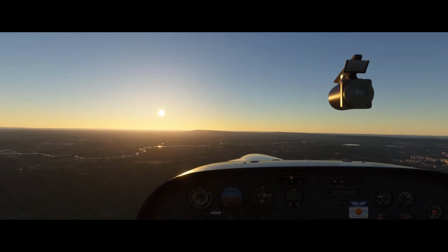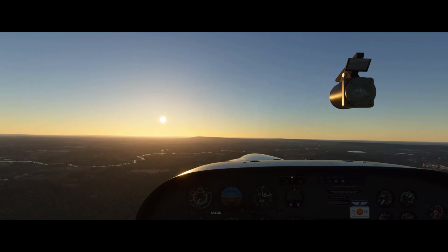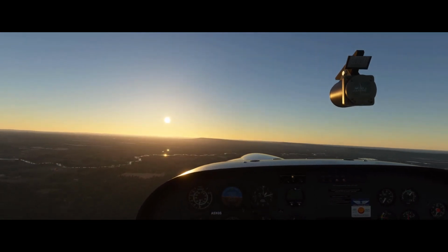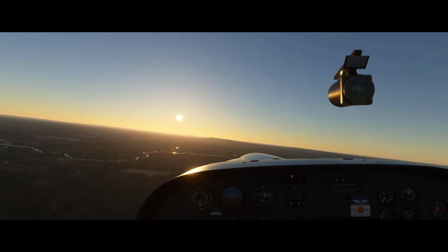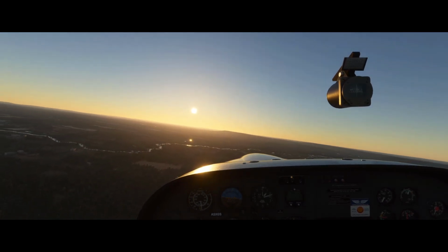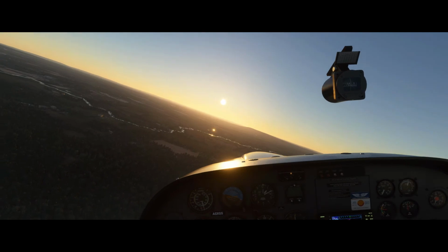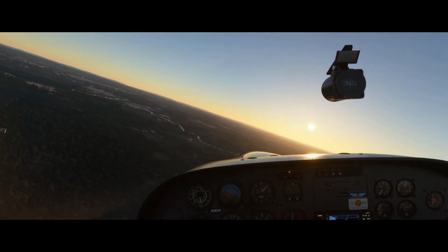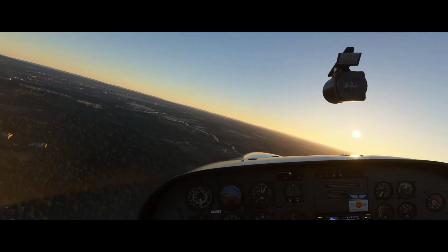So what we do here is we want to get into the white range for the flaps, which are on our airspeed. So I've pulled the power right back, maintaining altitude, and you can see we've just gone into 80 knots. We'll put the first stage of flaps in, and we'll descend at around, let's say, 70 knots. No power in at the moment, guys, so between 70 and 80 knots, and we're just keeping that descent going down.